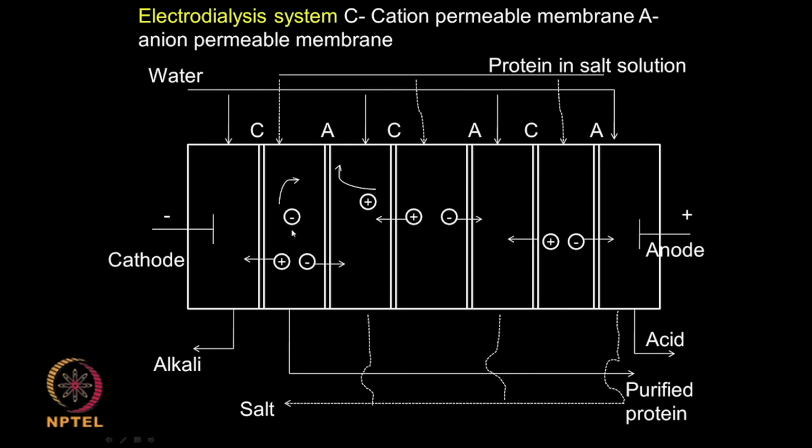RO, if you are closer to a sea and you need to apply very high pressures, whereas if you are closer inland and closer to an electrical power generating unit, then electrodialysis may be a better system actually. So, both have advantages and disadvantages, and you can select based on the conditions and what the requirements are.